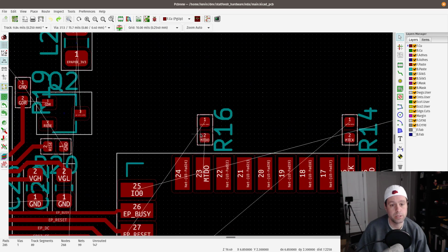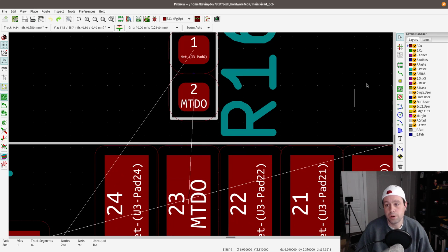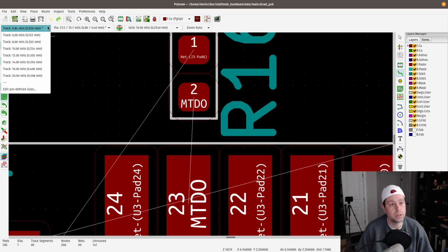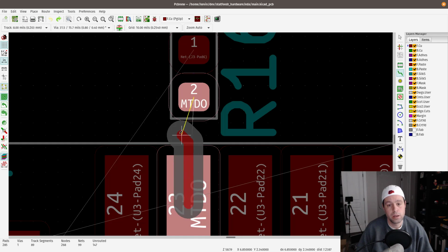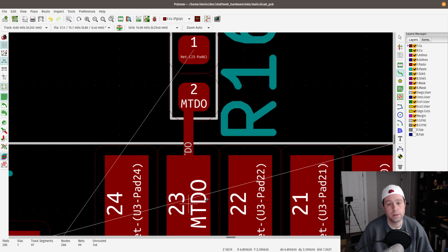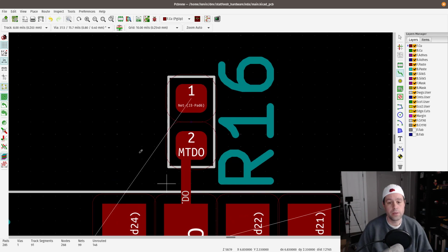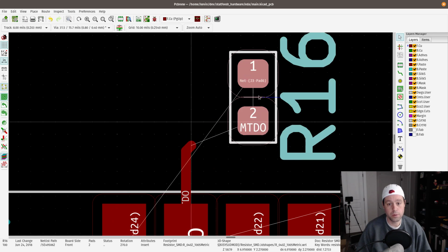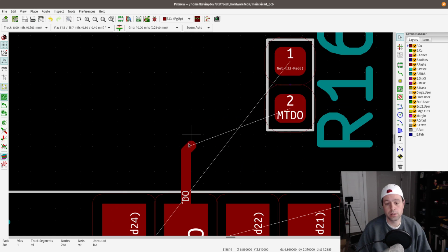Let's do R16 over here. We're going to go into trace mode. We want to select the trace that we're using. So I'm going to use 8 mils, let's say, and let's connect to there. That's connected. Now that trace is drawn, but if you come back later and say, oh dang it, I think I need to move this, I'm going to move it. It's not going to drag the trace around for you.